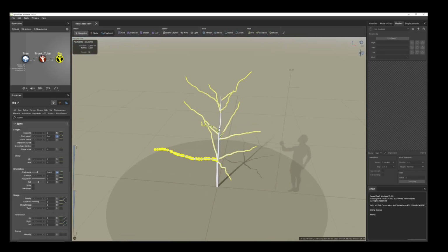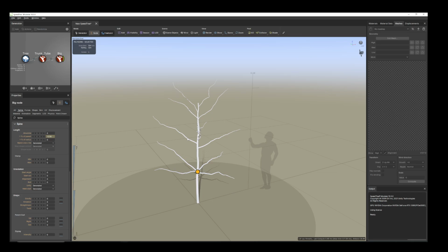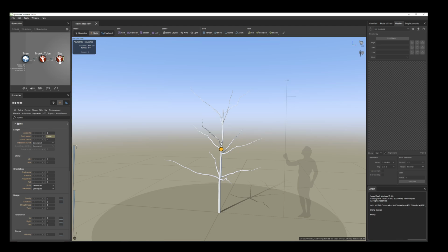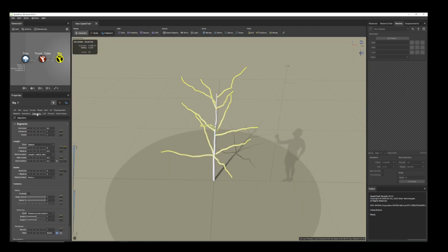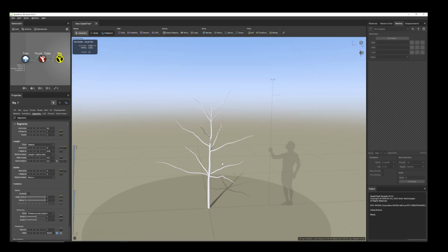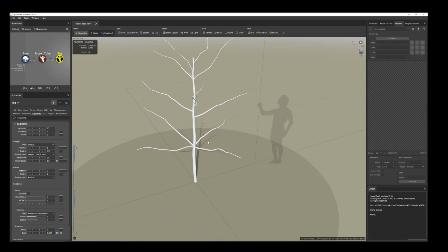Here something is long, so by pressing tab we can reduce or increase the length individually. Now I'll reduce some polygons from this: select the segment and reduce the absolute relative length. You can see it's getting reduced to 7. I'll keep it as this, 2.9K.